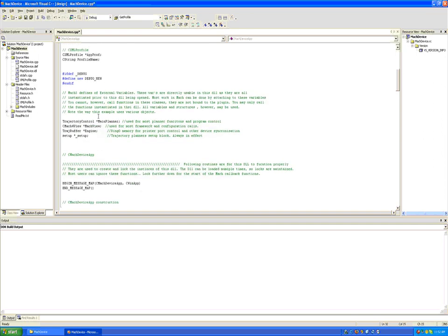We have instantiated as well 4 pointers that are automatically filled at the time that the DLL is started up. These 4 pointers represent 4 of the major classes of Mach3. There is the main planner, used to run most of the code in Mach3. Mach-View is used to control the windows and frameworks. Engine is the ring 0 variable block for the printer port and some other operations.